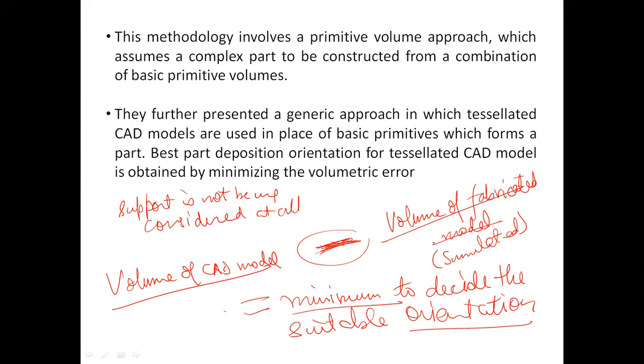You are not considering the support structure generation in this evaluation anywhere. Secondly, when the tessellation of the CAD model happens, there is bound to be a volumetric error, and then during the fabrication stage, due to varying layer thicknesses, you can have even bigger volumetric error.